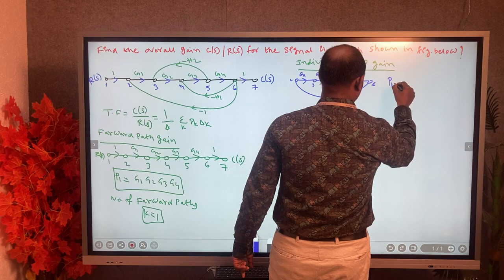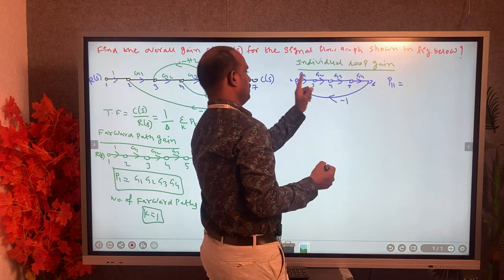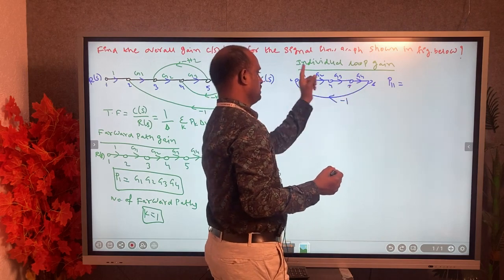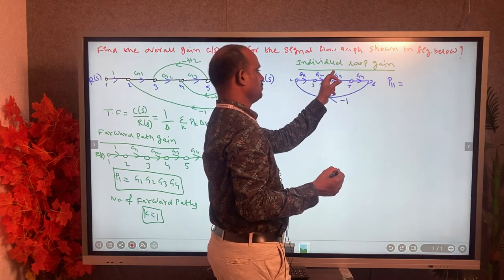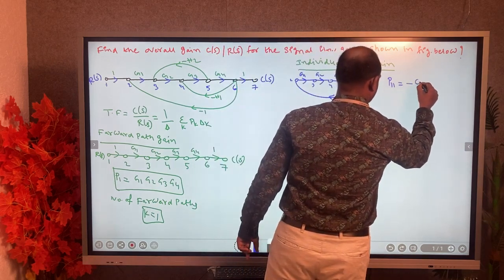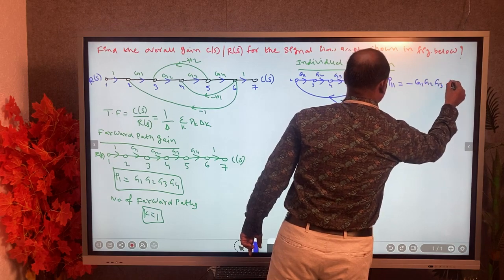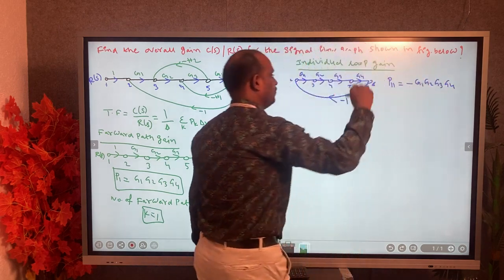So P11, we will discuss what P11 is. You multiply all the transmittances of the loop, that is G1, G2, G3, G4 into minus 1, which equals minus G1 G2 G3 G4.